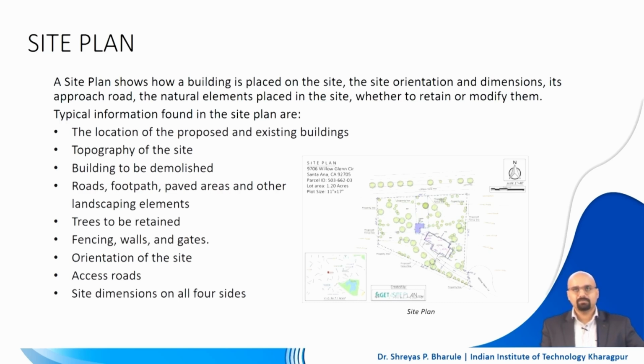But for each amendment, each change that will be there, there will be a separate layered drawing. That is something an architect needs to be sure of, so that it can be communicated well on the site. People who are involved in execution of these particular layouts or elements of that building or area will be much more careful, and will be informed with the help of that particular drawing.